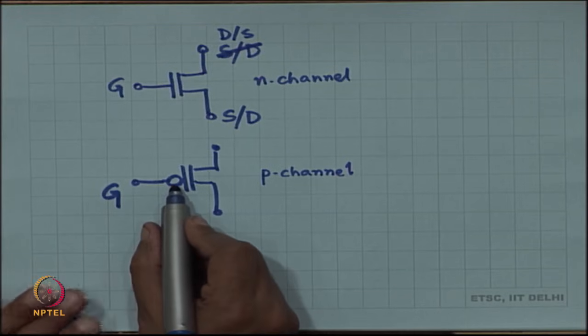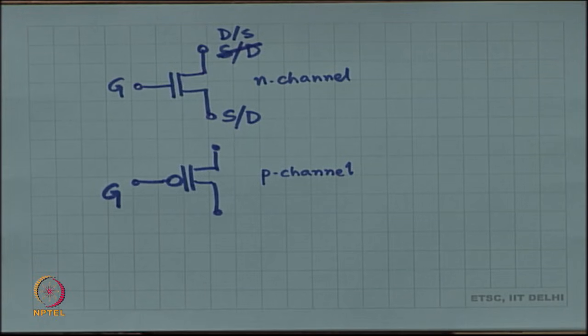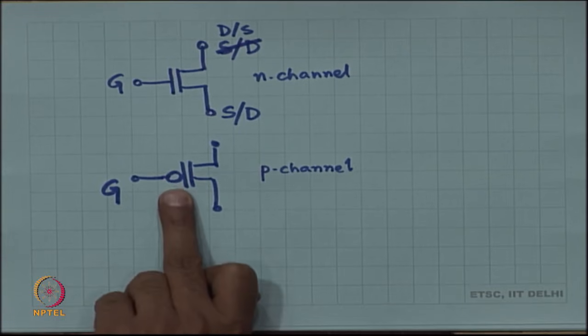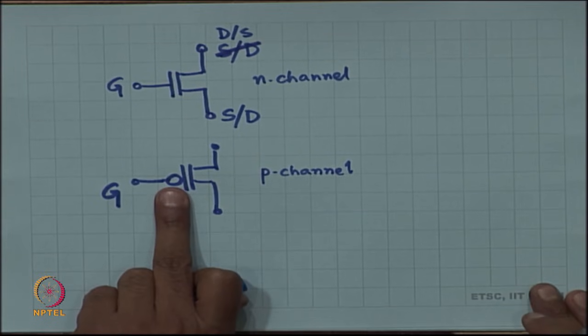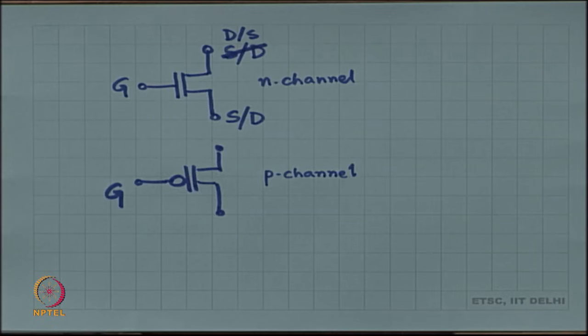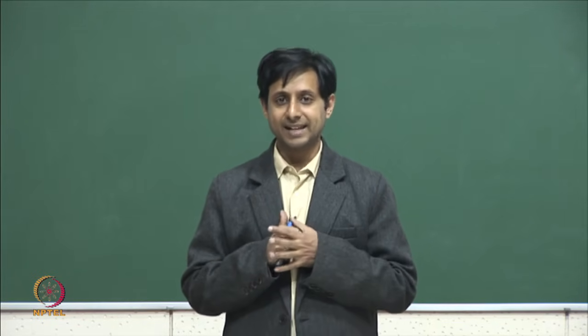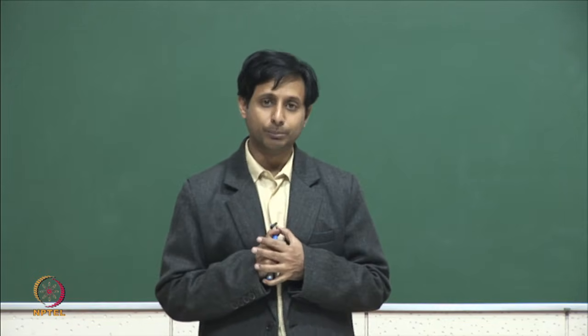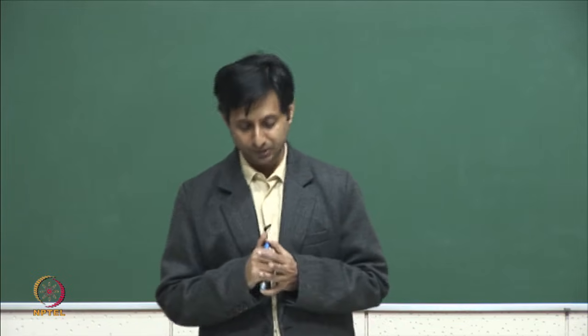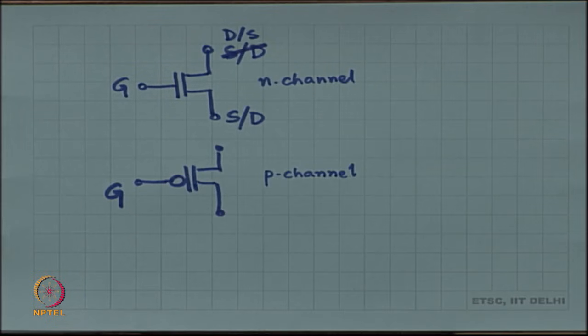So, there is a bubble, right. Remember your digital circuits, whenever you put a bubble, it implies a not happening. Okay. So, these are also symbols for the MOSFET, but I remind you that these symbols are going to be used only under situations where the MOSFET is going to be operated as a switch. So, that means digital circuits. So, these are symbols used primarily in digital circuits.